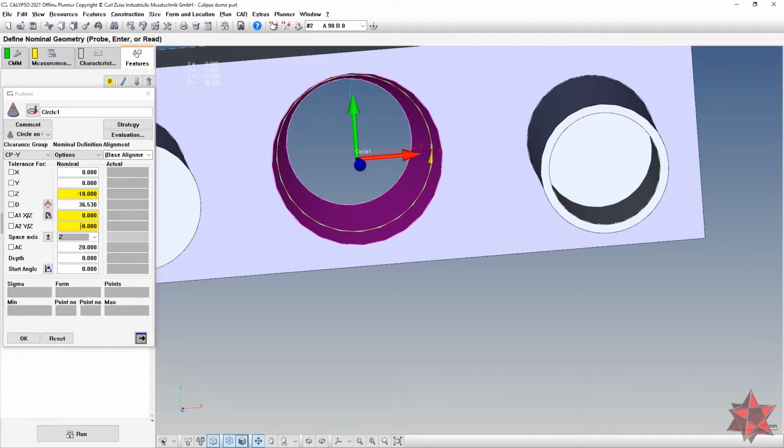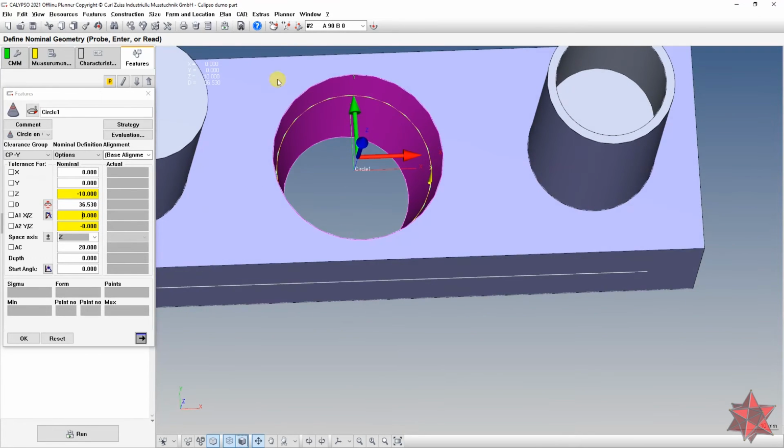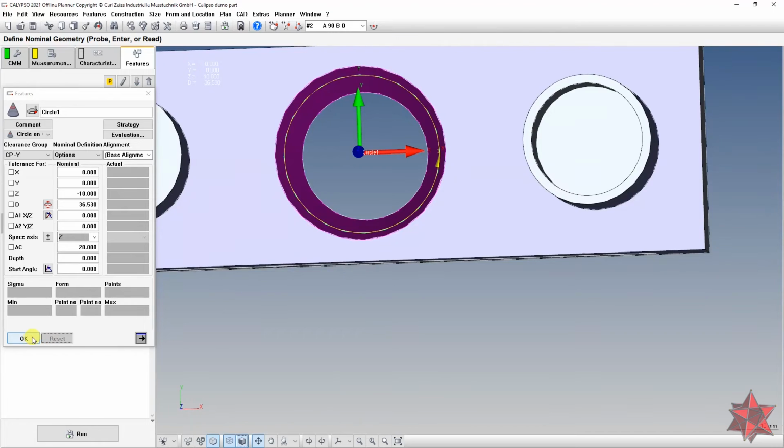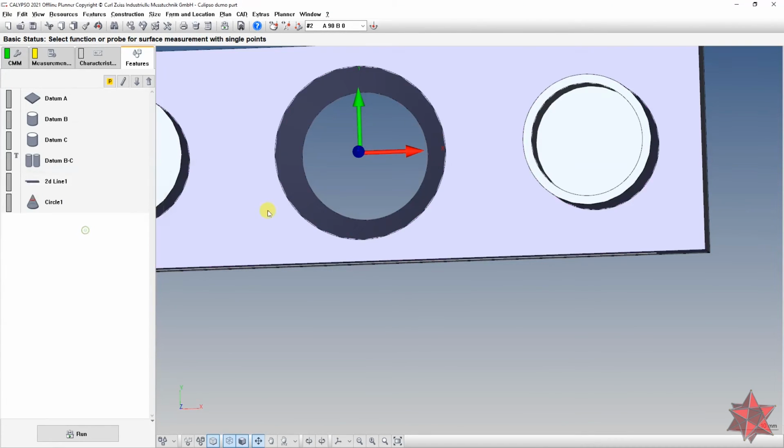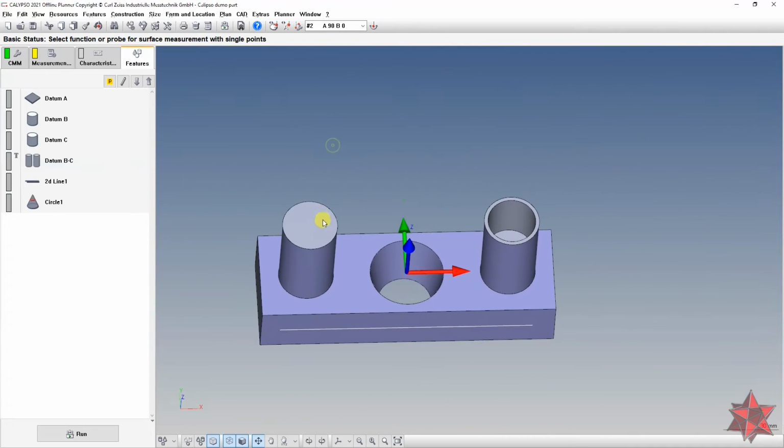Okay, so now again it takes the formulas from the plane, A1 and A2, with the rotation and everything. But I will not use this because I don't need the plane, right? I only showed you the example, but I don't need the plane because this is datum A, and from the datum it knows exactly where to go.